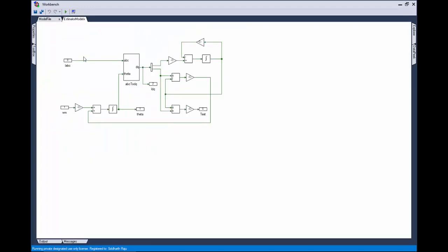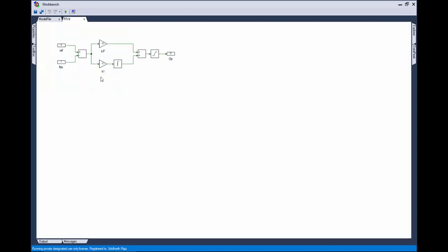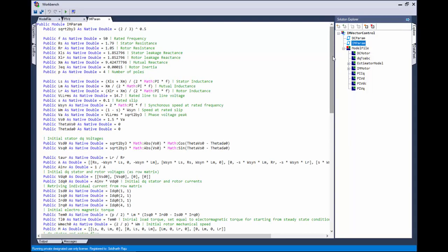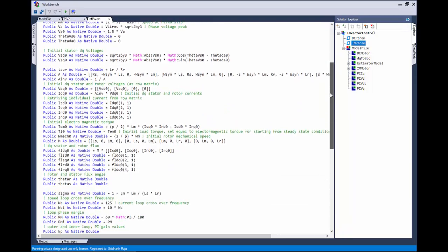The DC motor is run in torque control mode to emulate a step load, to ensure that the motor speed is maintained constant. The induction motor is operated in speed control mode with an inner current loop to maintain the motor flux and torque and an outer speed loop.